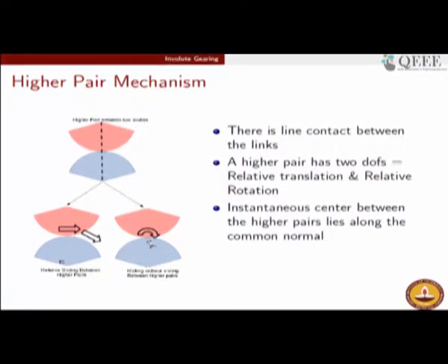It is just like a wheel which is gripping the surface. So, the point of contact, whether you assume it to be a point on the blue body or on the red body, either way has 0 velocity. So, the point of contact essentially becomes your instantaneous center. In dealing with relative rotation, or rolling without slipping, the point of contact is the instantaneous center.